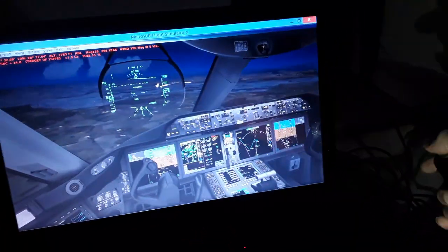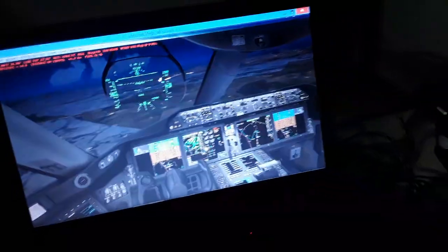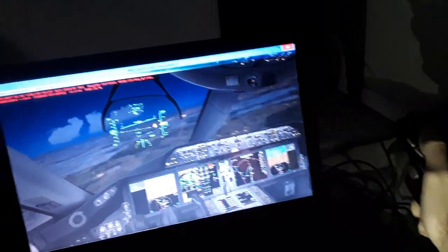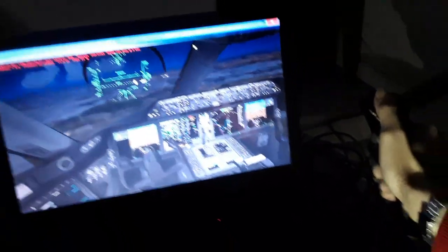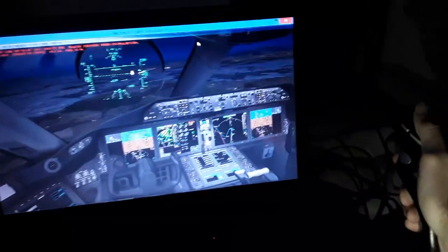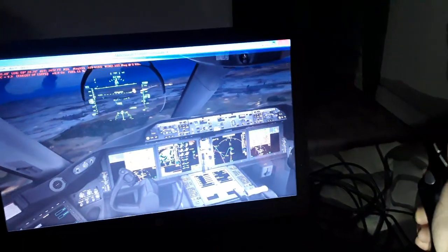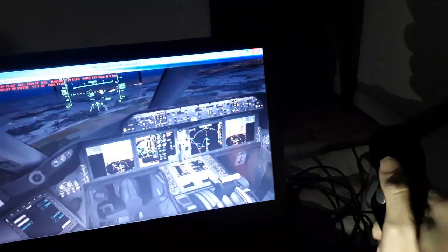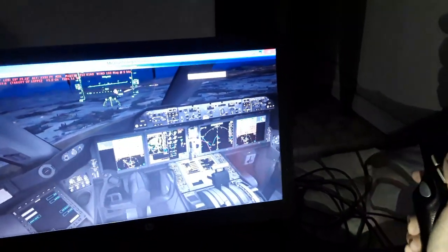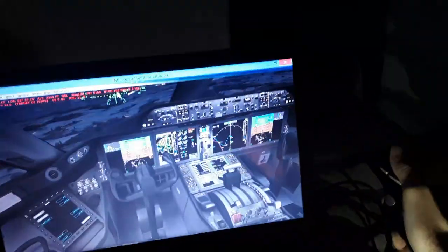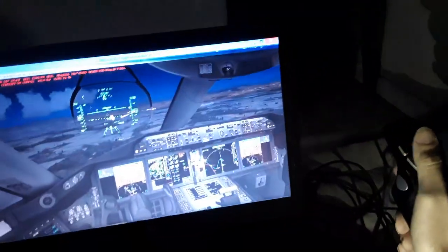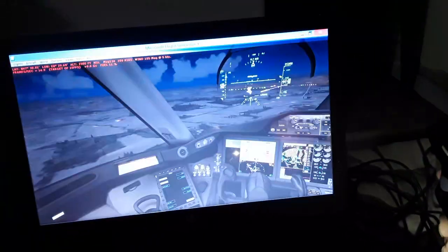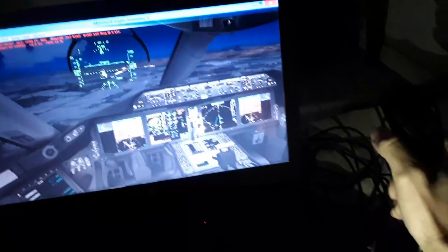So you can see the runway, it's over here. We need a little bit more idle thrust as we are approaching. Also a little bit of right rudder now to align with the center line of the runway. And a little bit of yoke control, rudder pedals, also control wheel, aileron, spoilers, elevator as we are approaching the runway for landing.